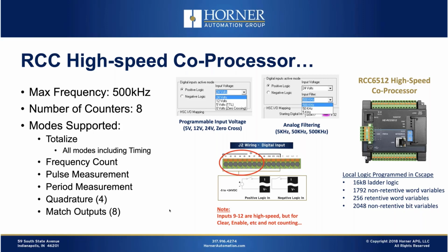And there's some other advanced things we're doing here. One of the advanced things is we have a much more flexible input voltage for the inputs than we have on our standard products. Keep in mind, our standard products most of the time are interfacing with 24-volt signals. Sometimes they're 12-volt signals if it's a mobile application or just a 12-volt battery-operated application, for instance. But this product can support not only 12 volts and 24 volts, it can also directly support 5-volt levels as well as zero crossing 0-volt levels as well.